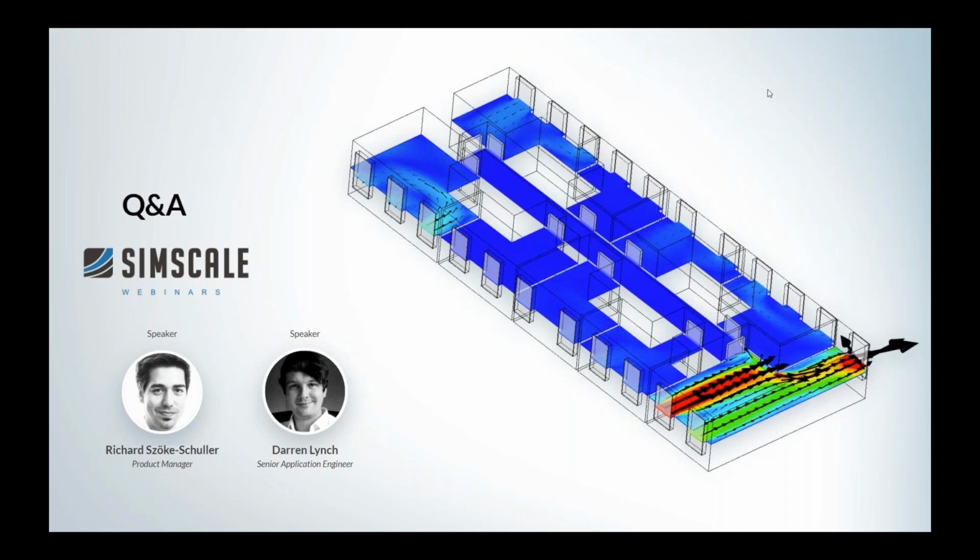Can you calculate flow rates through windows, Richard? Yes, obviously you can do that. The core results that you get from CFD are temperature and velocities. With the post-processor, for example, you can compute bulk calculator values that compute the average velocity and the integral of certain quantities over surfaces. So you can pick the surfaces in the post-processor and it will integrate the values for you, or for example compute the average velocity and also flow rates.